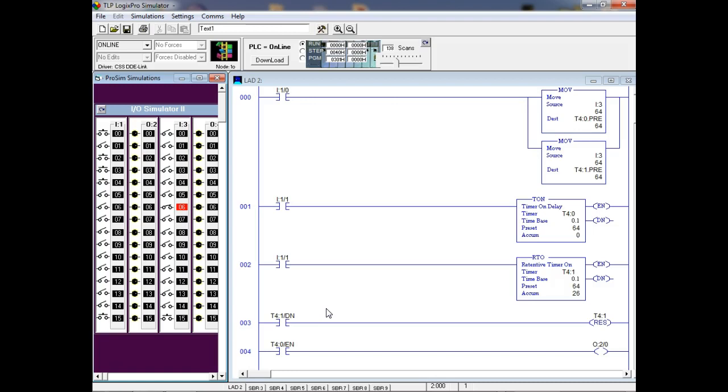Are we okay? So y'all see the power of the move though, and y'all see the difference between a retentive timer and, of course, what else we needed, an on delay timer. The move has enabled us to do what? Change a constant into a variable.